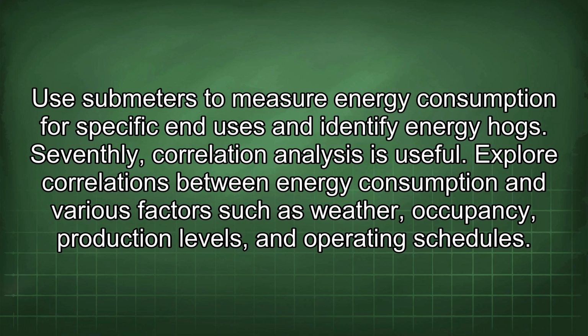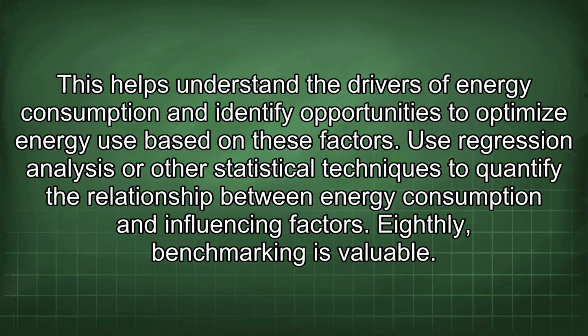Seventhly, correlation analysis is useful. Explore correlations between energy consumption and various factors such as weather, occupancy, production levels, and operating schedules. This helps understand the drivers of energy consumption and identify opportunities to optimize energy use based on these factors. Use regression analysis or other statistical techniques to quantify the relationship between energy consumption and influencing factors.